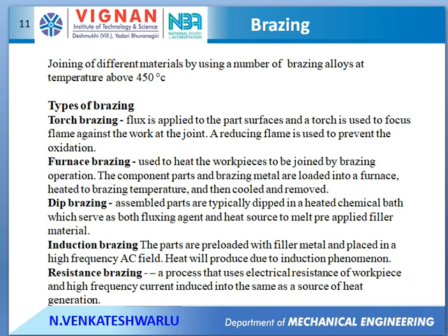Next is welding defects. We have several welding defects. Porosity occurs because of trapping of atmospheric gases. We can rectify it by providing proper inert gas. Next is slag inclusion. The slag particles are trapped inside. So we have to design the weld bead in such a way as to prevent the trapping of slag inclusions inside.